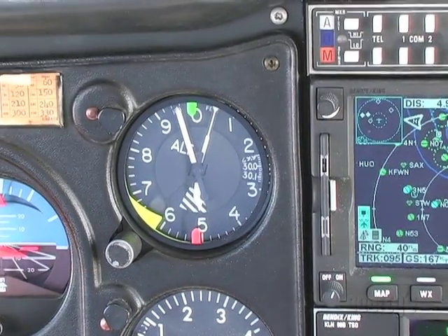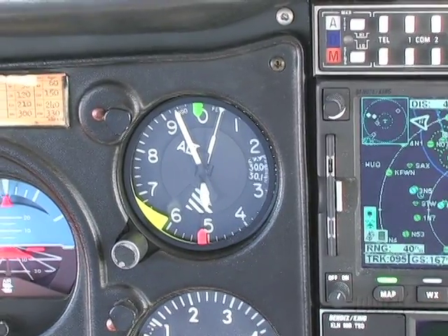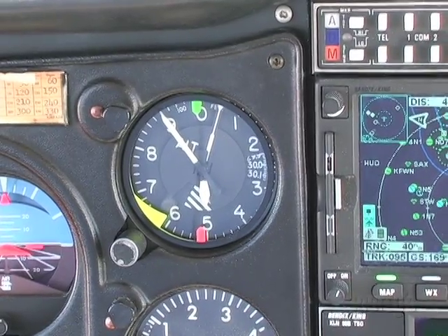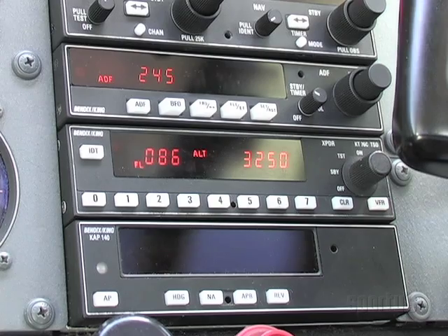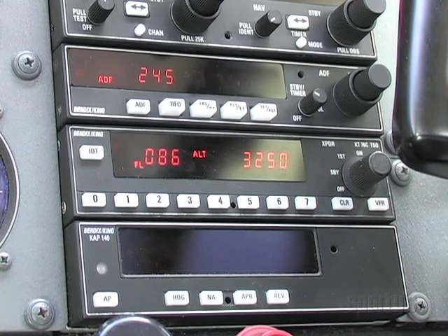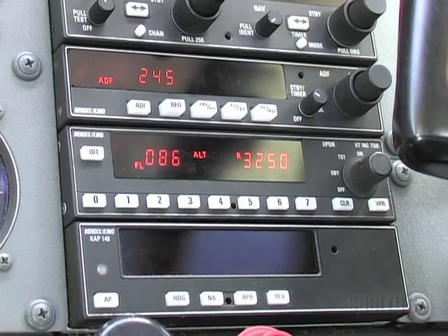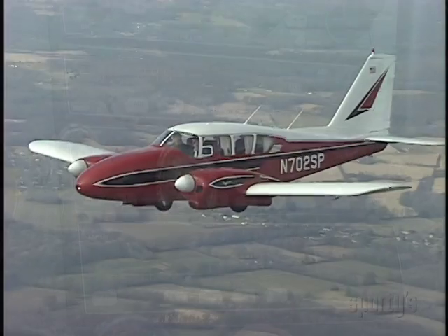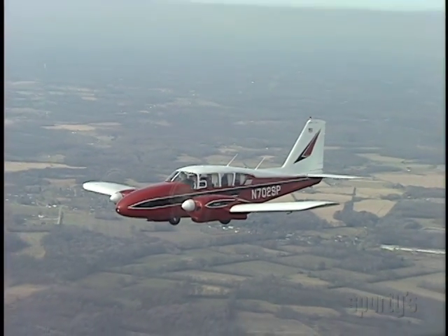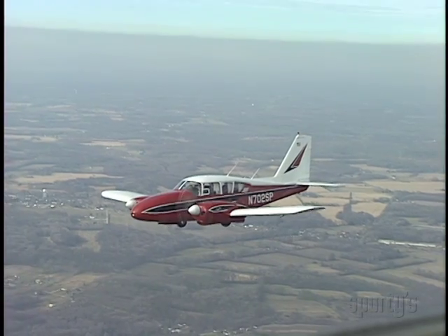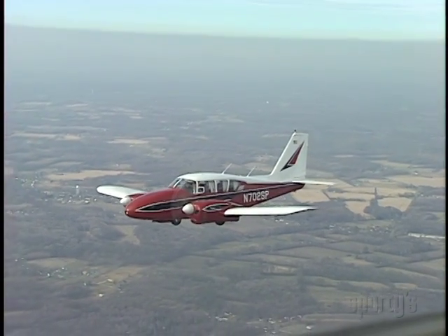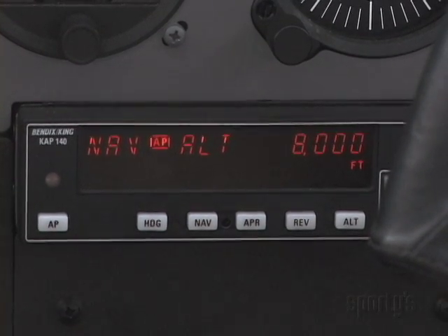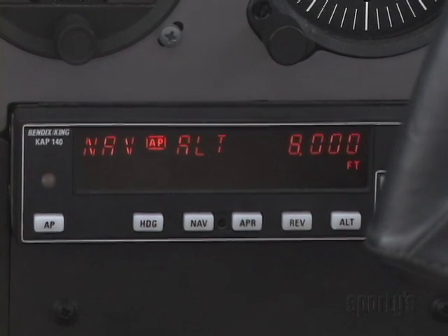If a pilot just wanders off altitude with no conflict with other traffic, the controller will usually give an altimeter setting and ask the pilot to check his altitude. If it is reported as bang on, yet the controller still shows it off the assigned altitude, then the pilot might be asked to quit squawking altitude. The most common altitude busts come on climbs and descents and occur when a pilot goes through an altitude that was assigned. This is what altitude alerters are for, though altitudes are occasionally busted even with that equipment on board.